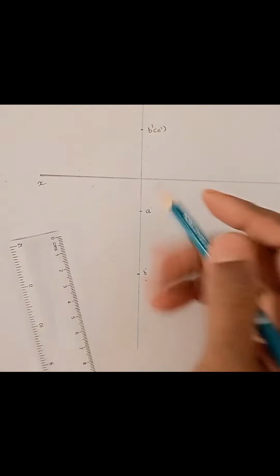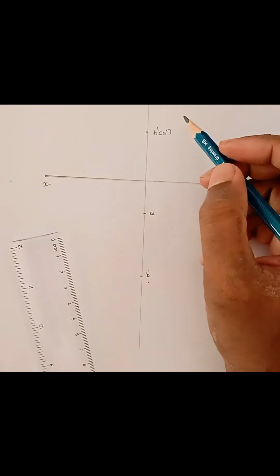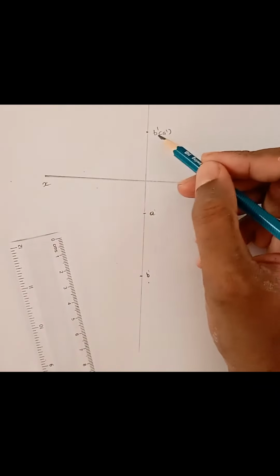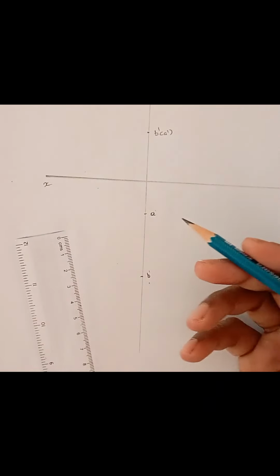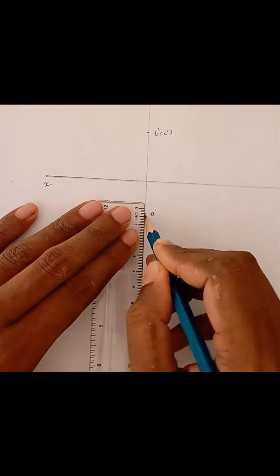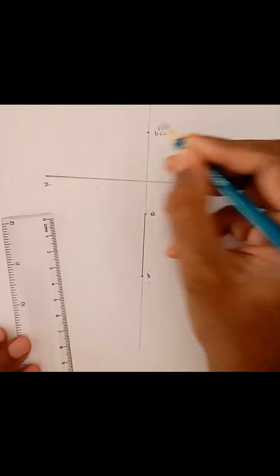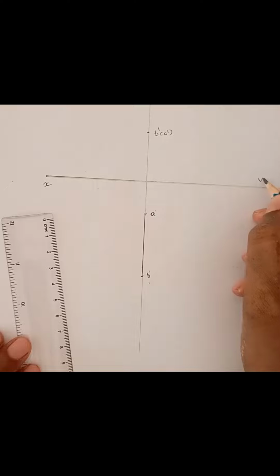There is no dash here. Sorry, there will be no dash, just A and B. Dash means B prime or A prime, B dash or A dash, and it's only in the front view. In the top view, we usually represent points by small letters without the prime or dash. So this is our line, 40 mm. This is our point, so you will see a dot or point in the front view. This is the vertical plane and this is the horizontal plane.